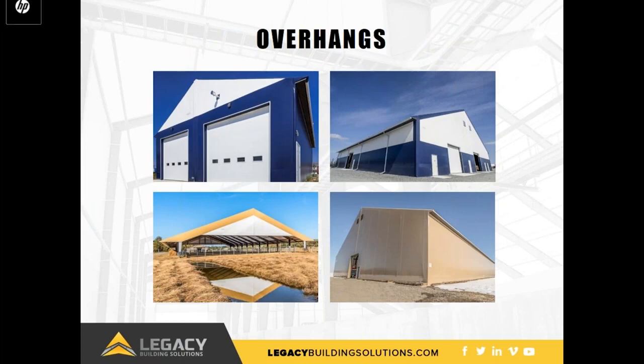Thanks, Dwayne. Overhangs are another benefit of the traditional gable-shaped rigid frame building design. In addition to giving the structure a traditional look, especially important when the building will be part of a larger campus, overhangs also provide the basis of a passive ventilation system. Overhangs with mesh soffit allow fresh air to enter close to the occupied level of the building. This air will naturally rise as it heats up and becomes saturated, exhausting out peak vents. In many cases, a passive ventilation system will provide all the necessary required circulation.